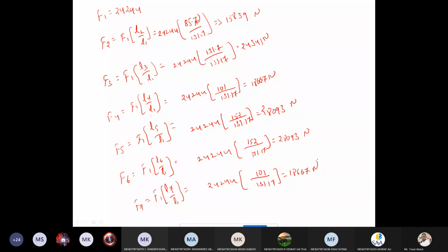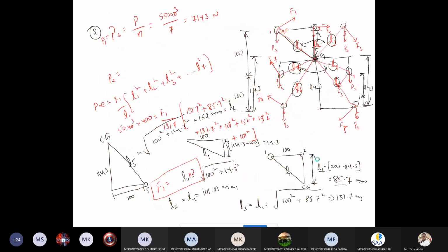Okay, Babu. So on each rivet, see the diagram. On each rivet, two forces are generating. One is a direct shear force, one is a secondary shear force. Here also, one is direct shear force, another is secondary shear force. Here also the same. It means on each rivet, two forces are generating.